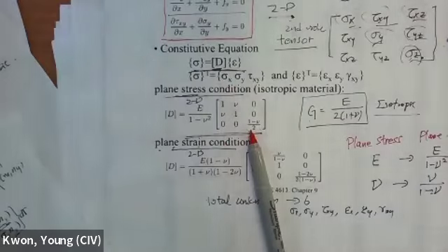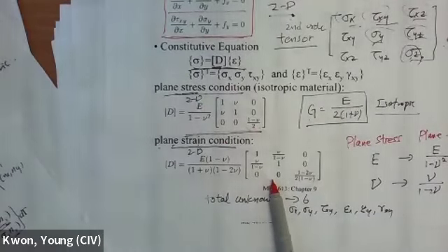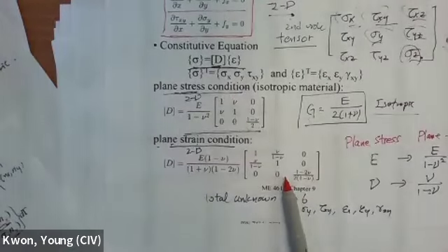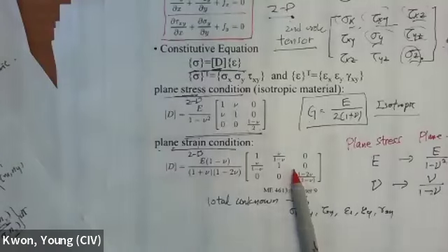Either 1 by 1, if this is going to be a 1D problem, 3 by 3, if this is going to be a 2D problem, and 6 by 6, if this is a 3D problem. 1 by 1, 3 by 3, 6 by 6. A square matrix. And this one does not depend on the choice of element, it just depends on the nature of the dimensional problem. And actually the property depends on the material behavior, isotropic or orthotropic, anisotropic, whatever. It changes, but not because of the selection of a different type of finite element. So 1 by 1, 3 by 3, 6 by 6.